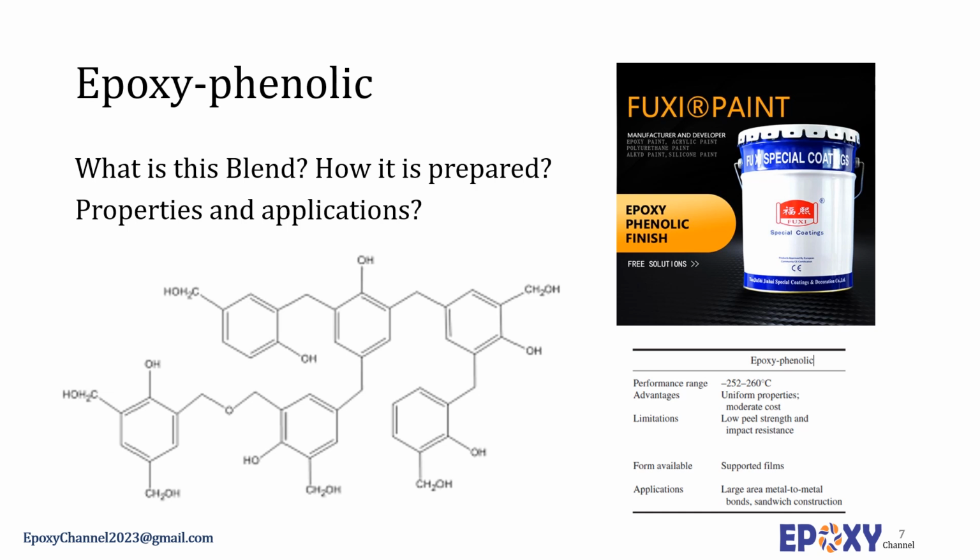Although the tensile shear strength of epoxy phenolic adhesives remains steady over a very broad temperature range, it is not as great as that of epoxy nylon or polyurethane adhesives at cryogenic temperatures. These adhesives are available as paste, solvent solutions, and film supported on glass fabrics. The adhesive films generally give better strengths than do liquid systems. Cure requires a temperature of 175 centigrade for 1 hour under 15 to 50 psi pressure.